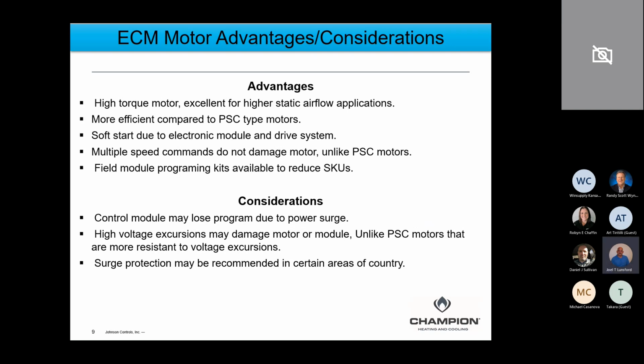In addition, multiple speed commands do not damage the motor. Unlike the PSC blower, if you were to put more than one speed command on a PSC blower, you're going to burn the windings up. On an ECM type of motor, multiple speed commands are absolutely normal, and it doesn't hurt the motor at all.